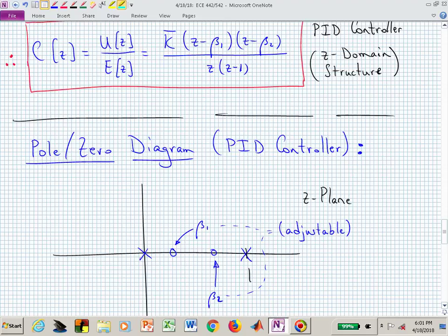What's the speed of that? It's fast, isn't it? It's really fast. And that's really there so that this transfer function is causal in the PID controller. The pole at 1, you told me, helps you improve steady state accuracy. And that's the I part of your PID controller. That's the integral part. That's giving you that pole at z equal to 1.